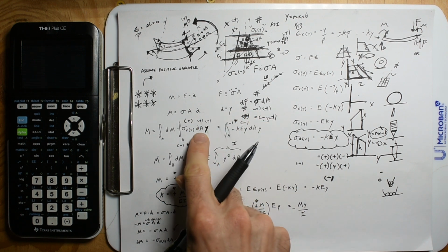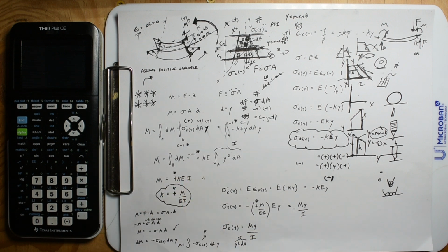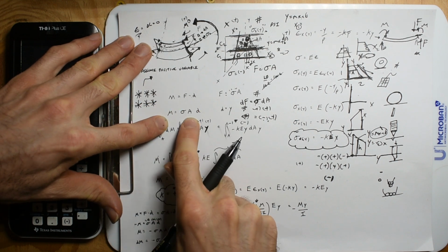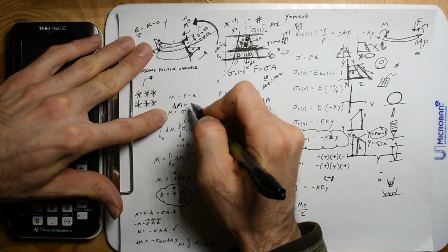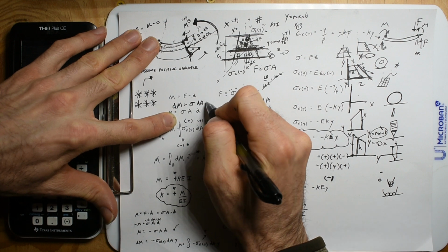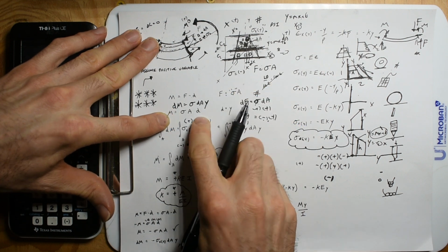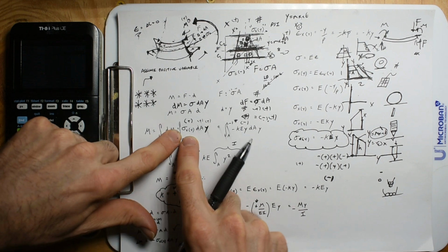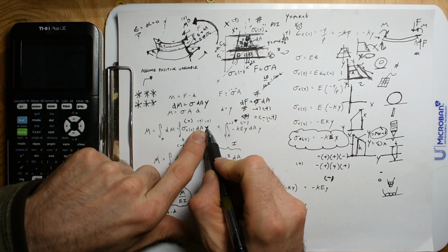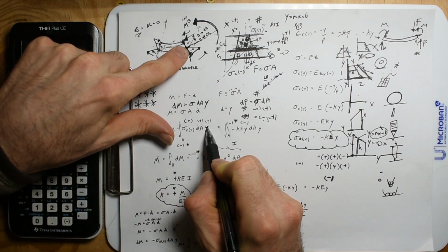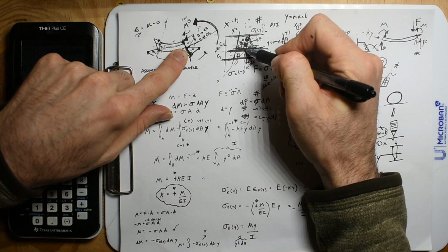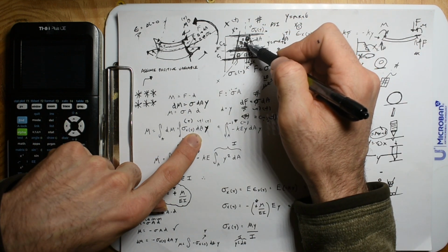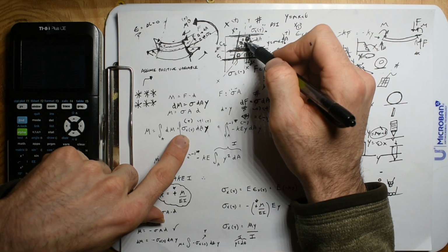And oh yeah, and this is where I got into trouble. I put all these asterisks because this is where you mess up. Is like, cool. So if this is the moment equation, a little fraction of moment is sigma dA, y. You know what I mean? Some distance y. And if we say that my distance y is positive on this face, so y is positive, the area is positive, it's in the positive x face, but sigma is negative.